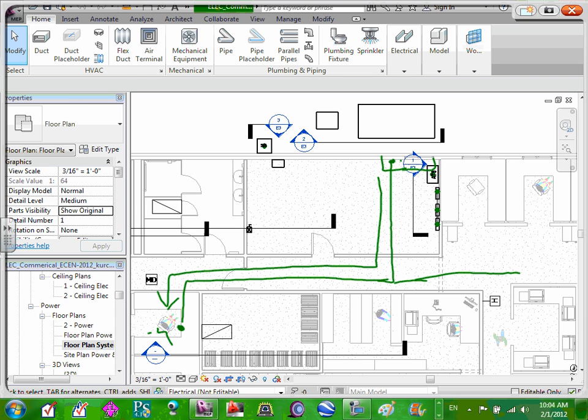And when water flows, we want our fire alarm system to know that. So there's a switch on that pipe that says, when water flows, I want to send a signal back to my fire alarm system. So there's a flow switch that tells the fire alarm system that the sprinkler system is going.